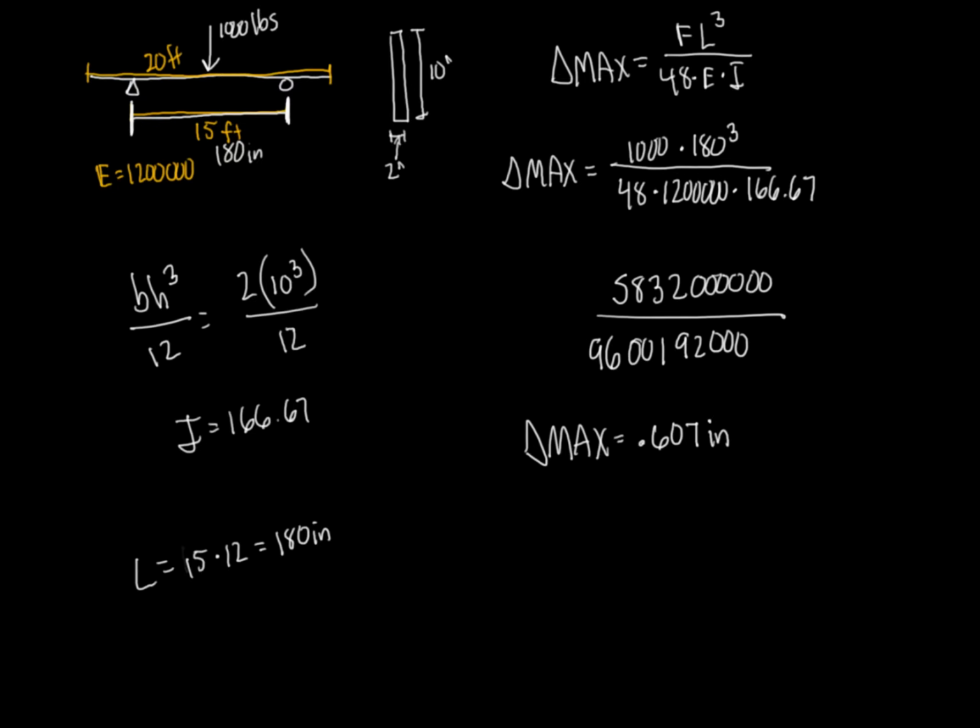Again, the biggest thing that people make a mistake on right there is that you forget to multiply by 12 to make it inches. Everyone wants to use just the 15. They want to plug that 15 in for that L and be done. You can't, because this is inches, this is inches, this is also inches. So it has to be inches. You have to convert it into inches. So just make sure of that. And again, that cube only happens to the L, not anything else.